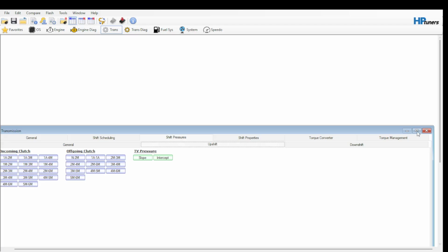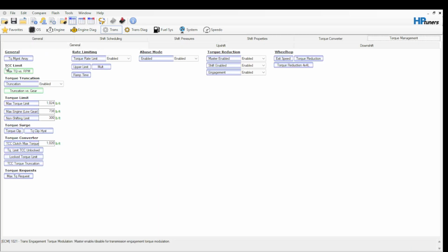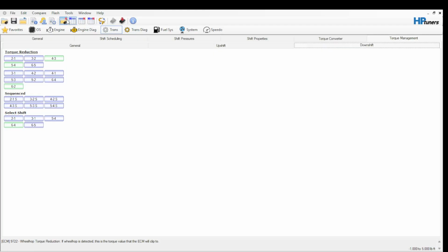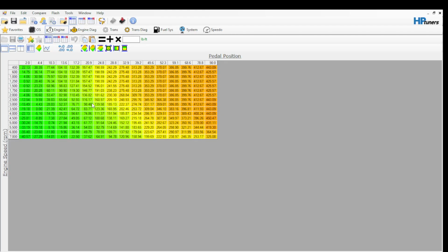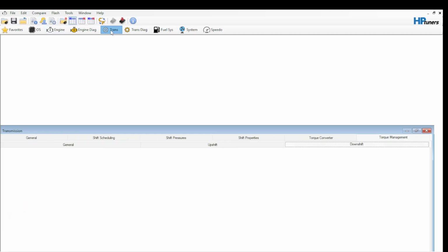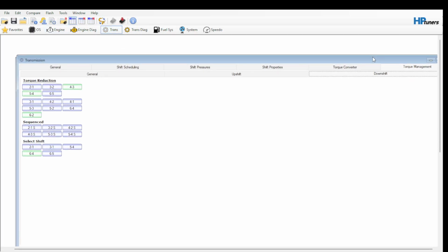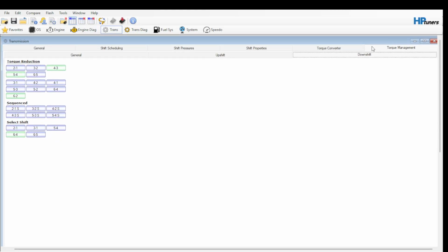Well, let's say that you're trying to shift without being on the throttle. The engine, depending on what your torque management is set to for your driver demand, could be a negative torque. Now, I've changed how drastic these negative values are because I've changed the ratio of my torque converter. But sometimes your torque isn't just 0, it could be negative 12 foot-pounds.